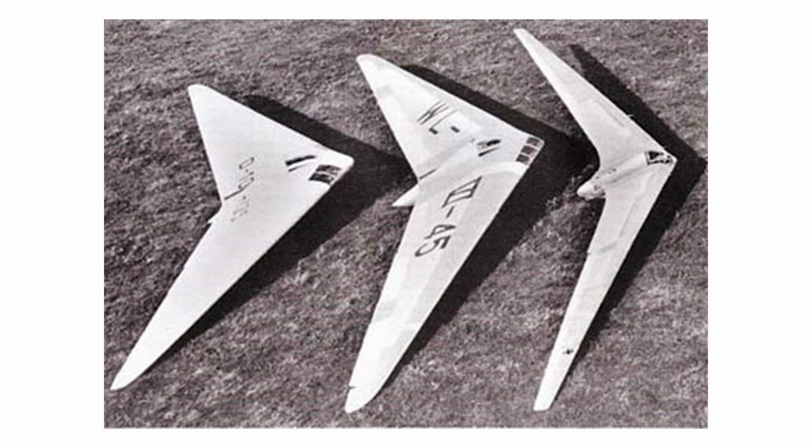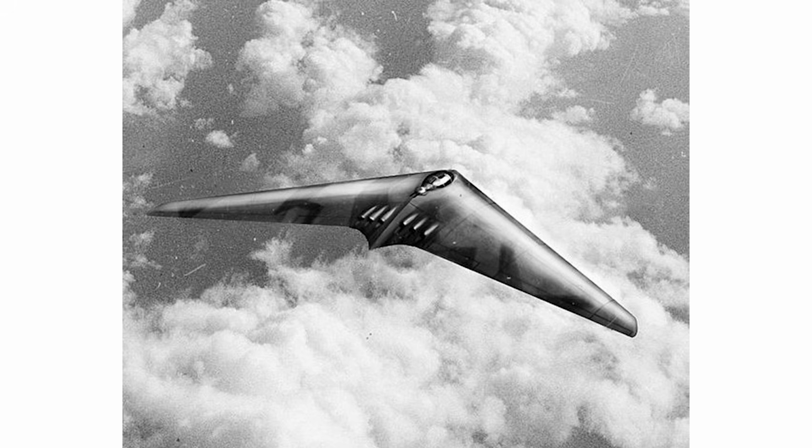Historically, the Horton flying wings utilized a highly tapered wing with a bell-shaped lift distribution over the span, which produced a small downforce at the tips. This ultimately reduced adverse yaw and allowed them to fly without a vertical tail, and achieving this lift distribution required extensive washout, sometimes up to 8 degrees, which we reviewed a couple minutes ago.